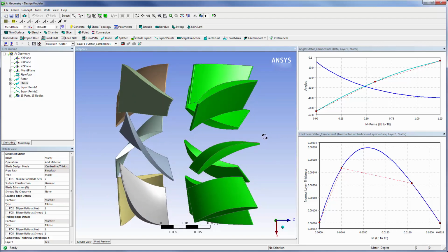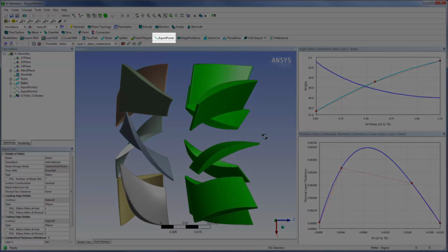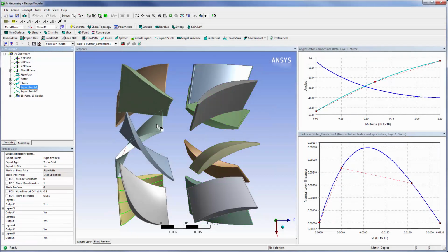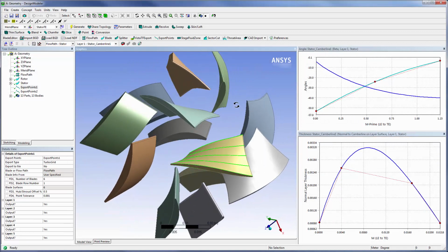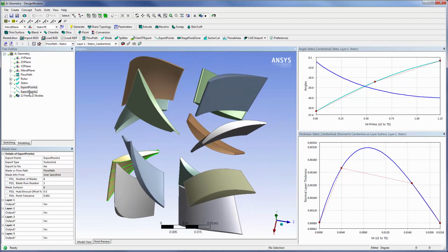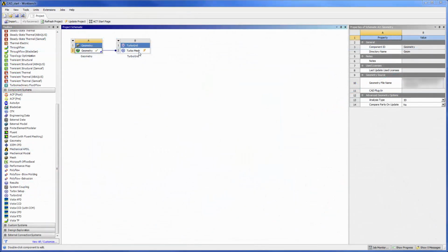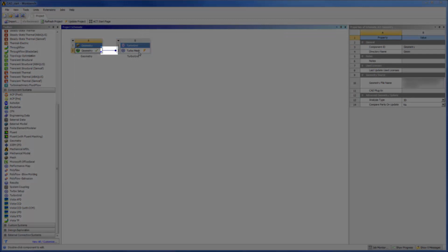In the past, TurboGrid only supported geometry definition by curve files, requiring that curves be extracted using the Export Points feature in Blade Editor. In this example, I've already extracted the rotor curve and the stator curve and transferred them to TurboGrid through this cell connection in ANSYS Workbench.